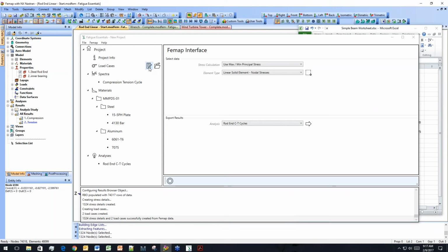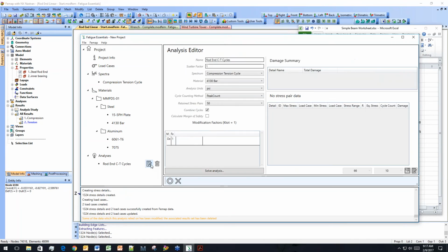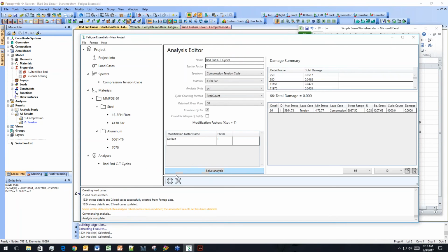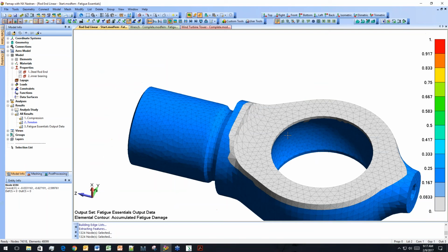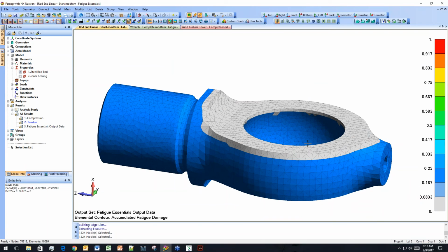Brian, ever grab anything on the inside? No, because the high stresses are going to be on the surface, and a crack initiates from inside the part mostly if you have a flaw, and that's not what you're checking here. So in the audience, is there some learned expert on fatigue that says we always look on the inside of the part too? Let me know, I'd be curious. No, 100%, it's always on the outside.